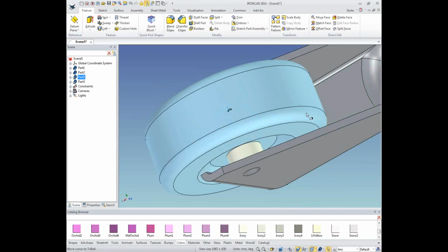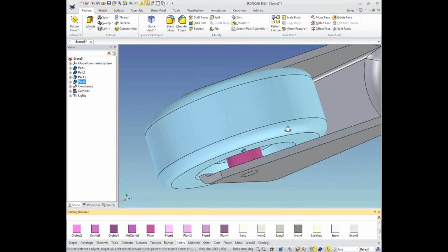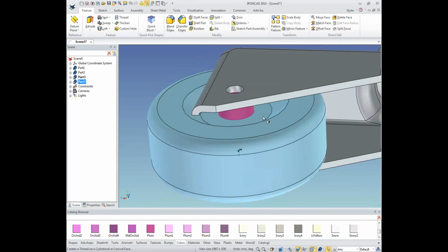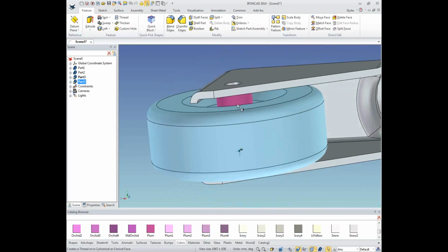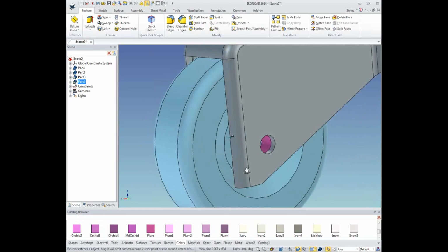And you'll notice that these have a little white symbol next to them on the parts. That means they're linked. So anything I do to one, if I change one part, it'll change the other. If I resize the part, it would resize both of them. So that's the linking that's involved there. It's very handy.